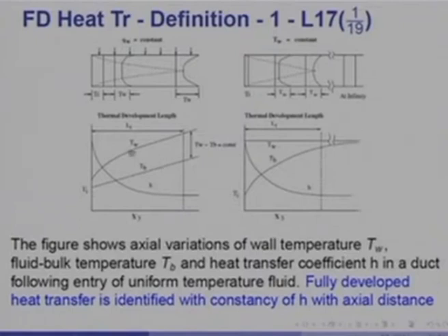We of course assume that the velocity profile is fully developed, may or may not be fully developed, and therefore, this shows the thermal development of the temperature profile. You can see it started with a uniform temperature, but then as the heat flux comes in, it assumes a curved shape. Of course, the gradient at each section would be constant because q wall is constant. Ultimately, the profile would become like that.